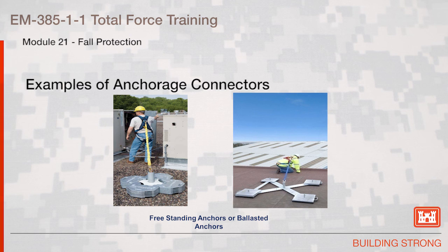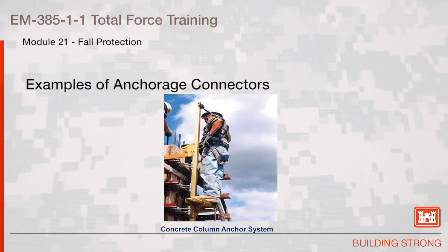Portable anchorages are also available that can be either ballasted or weighted down with steel, that allow temporary anchorages to be installed on roofs. For personnel working on concrete formwork, special anchorages are available that allow the workers on the face of the formwork to have an adequate anchorage.